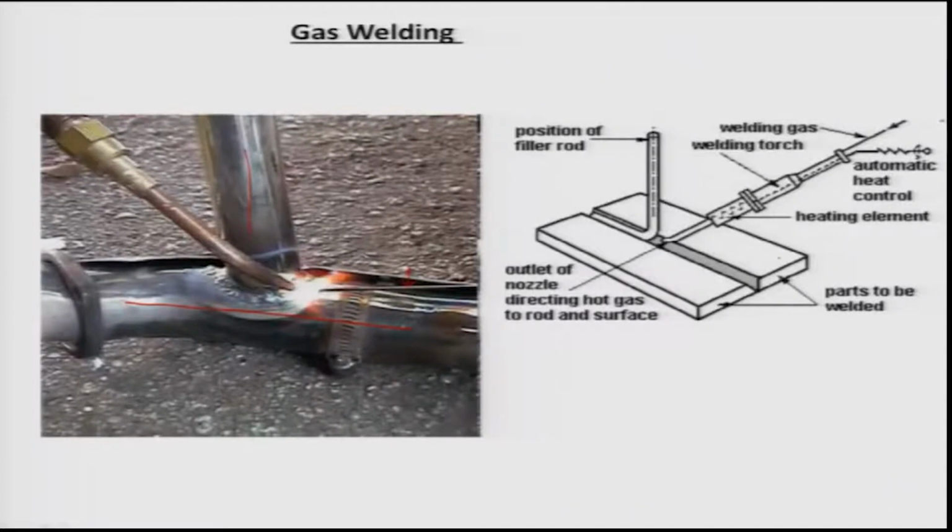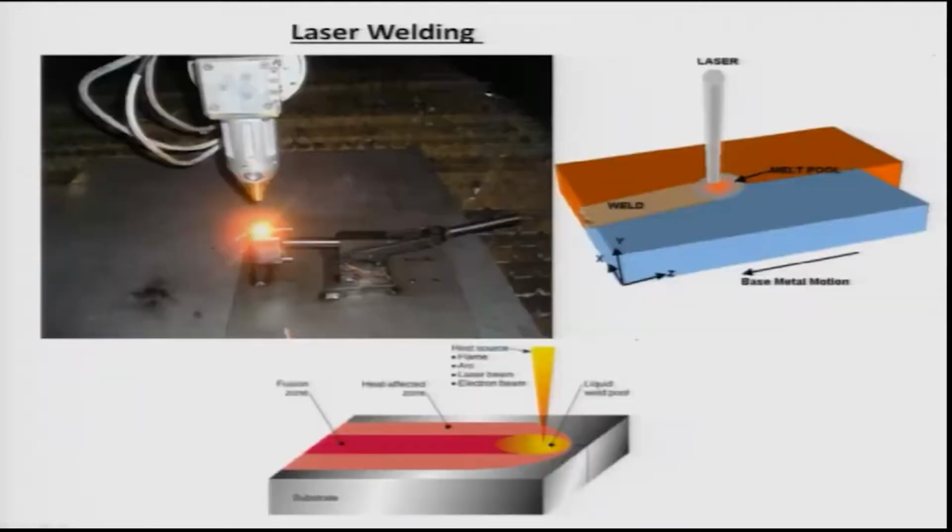Again, because welding is happening only in a small region, the bulk of these pieces remains solid, therefore there is an enormous number of heterogeneous nucleation sites present on the surface. So the only issue here is how the nucleating solids grow into the liquid. So those are the basic aspects.